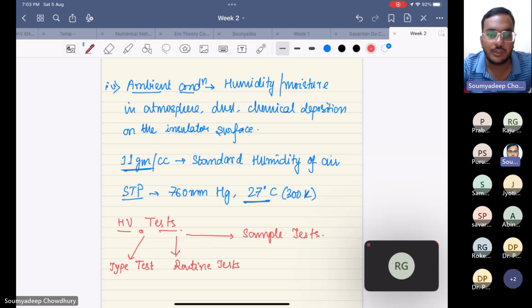on the string insulators. Then we have the RIV or radio interference voltage tests on these insulators, because mostly these power lines will run close by or nearby to the telephone communication lines also, and there can be some interference from these communication lines which can affect the performance of these insulators. In RIV tests, we test with the high frequency component, and we see what the performance of the insulator is.